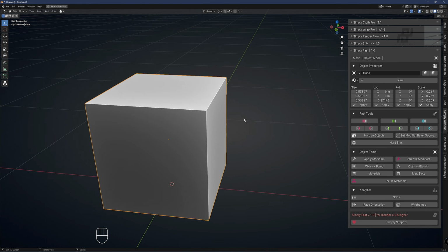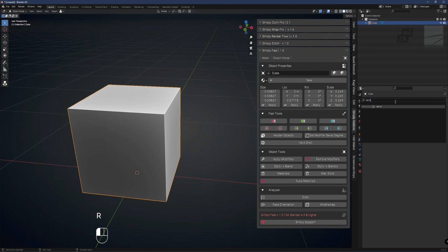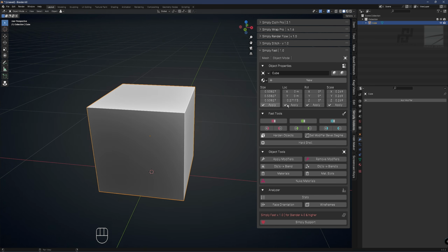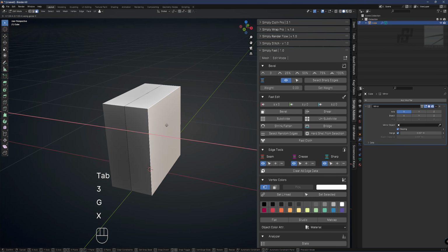What we can do in the main way is go to the modifier stack, hit add modifier, search for mirror, and then apply a mirror modifier. But these steps are again too much, so you just hit this button. So we want to mirror the object on the X axis in this way. That's it. And now I can start working.